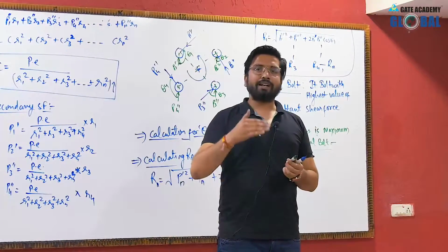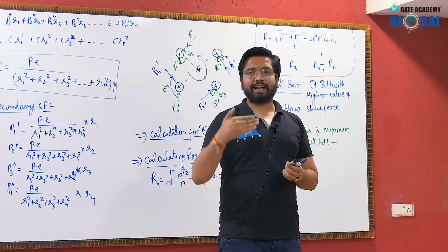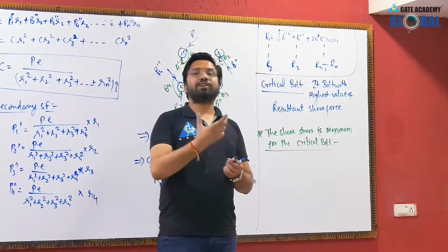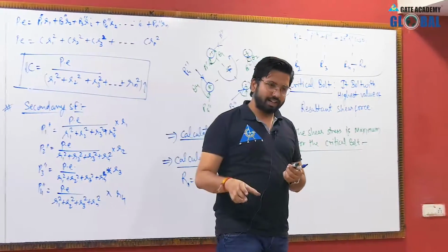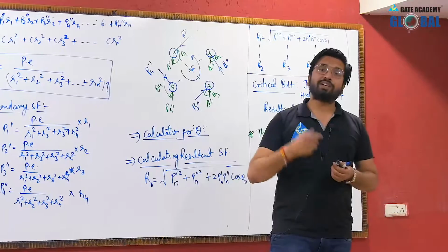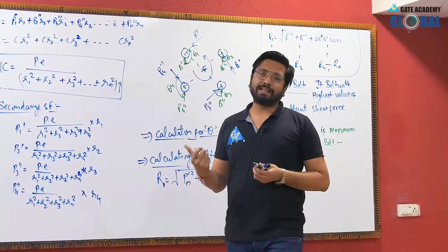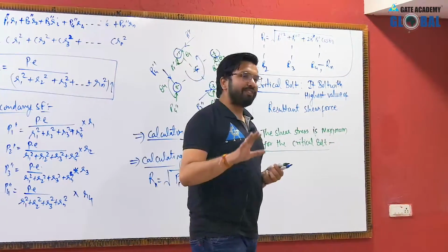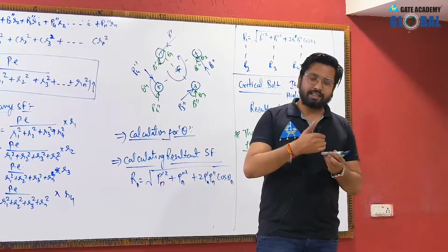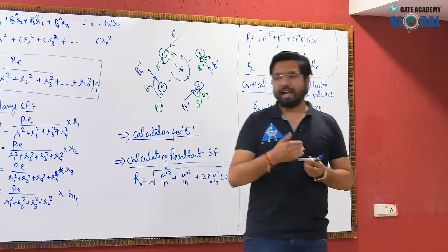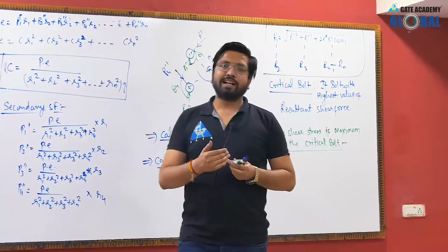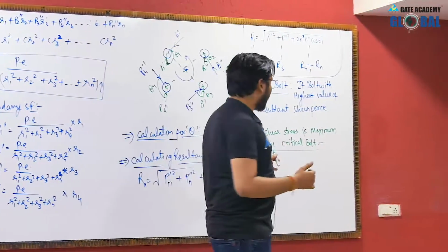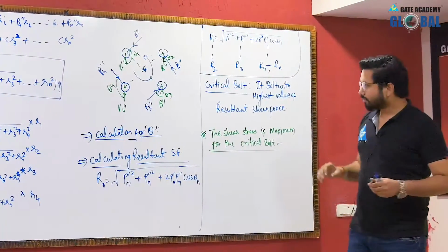bolt. Okay, but if core diameter is calculated, then finding the major diameter based on the value of the core diameter requires a manufacturer catalog or some empirical relation based on the type of thread being used in the bolted connection. Okay, so that's why for the safer side we will always consider that shear is there in the shank portion, and as the shear is in the shank portion, then we will always have the value of major diameter. Now